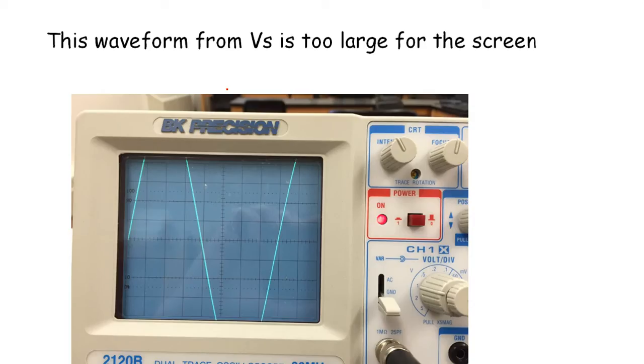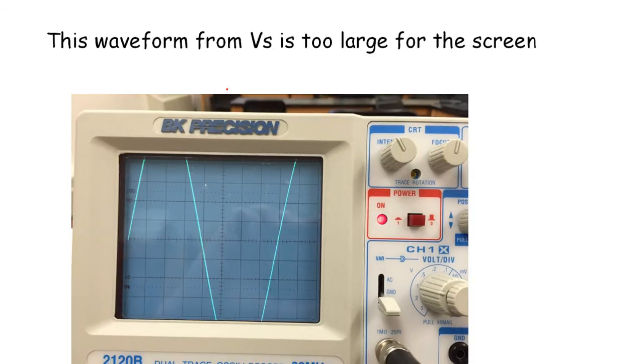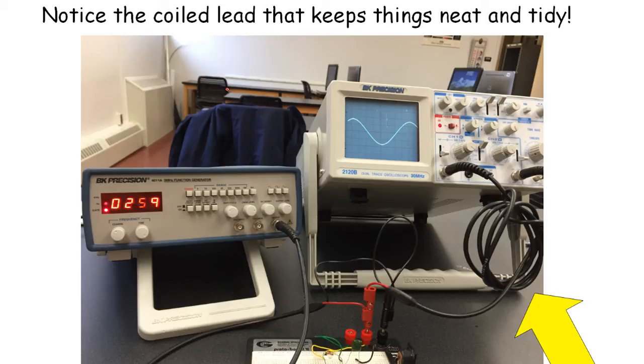Okay, well, look at this waveform. It's cut off just like in multisim. What do you do? You adjust this knob, you adjust this knob until it gets to be in range. And look at that sharp edge up there. That means that the function generator that we have is not giving a very good sine wave because it's got this little edge on the end. Normally that's not going to cause us a problem, but that is a bit of a distortion, and sometimes it'll come up if you're amplifying or something.